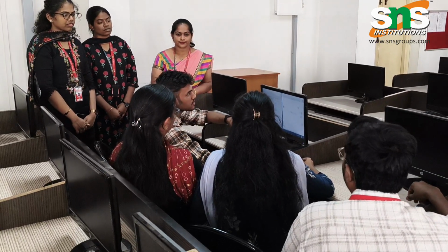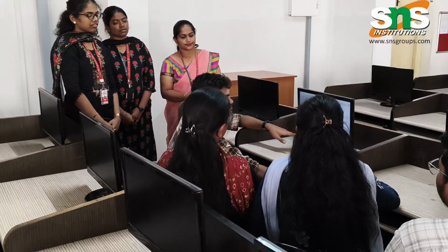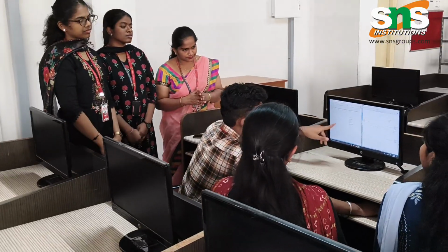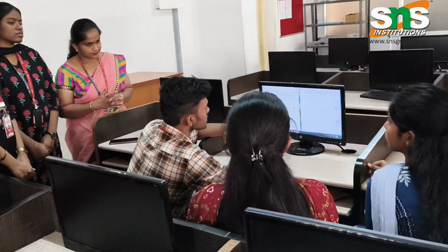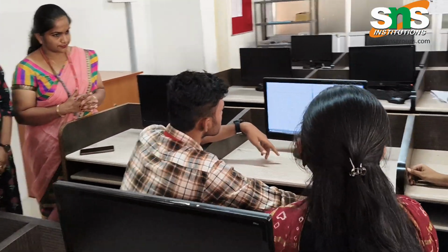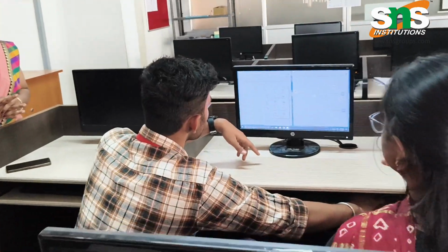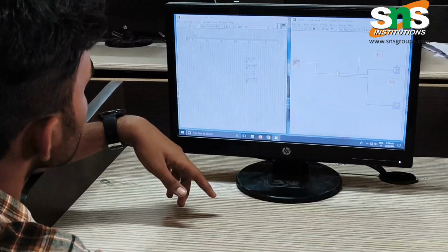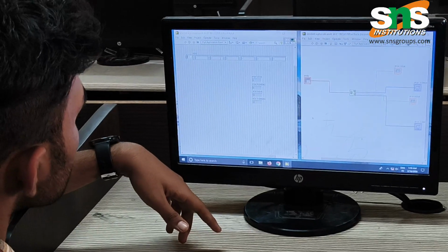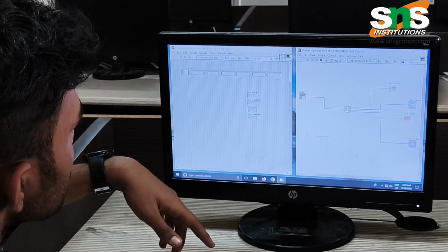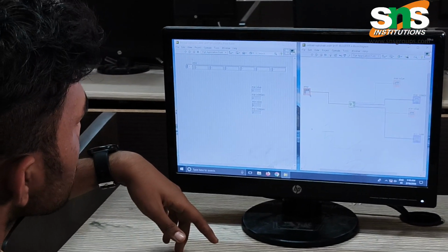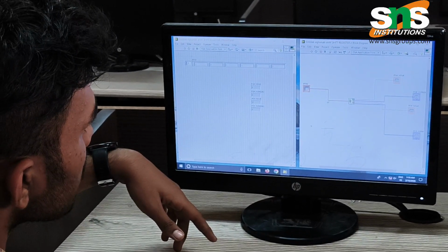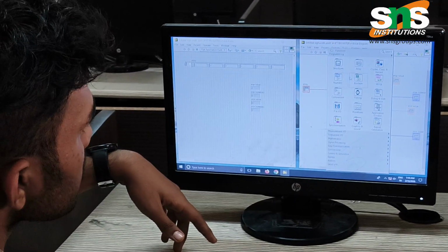Now we are going to see the shift register using array and string function. First on the front panel, we should pick the control palette and select the array to insert an array. After inserting an array, the array will appear on the block diagram. We should extend the array to 5 elements with numeric constants. Once the array is connected, we should open the block diagram panel.